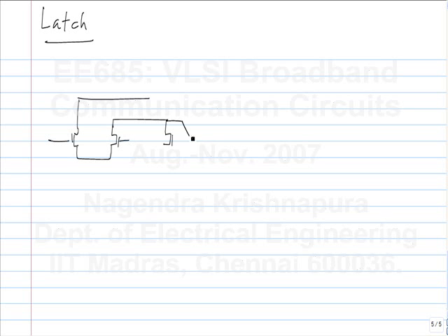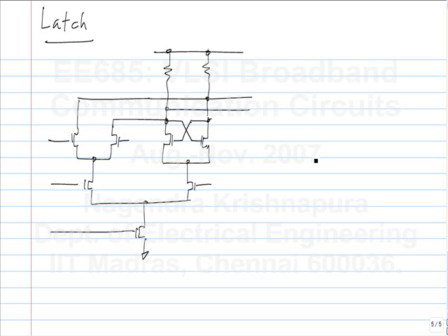The positive feedback connection is easier to write if you flip the orientation of the transistor. So this is the latch, and you can see the cross coupling. This cross coupling is the positive feedback. Let me change my notation. So this is Q, and this is QN.